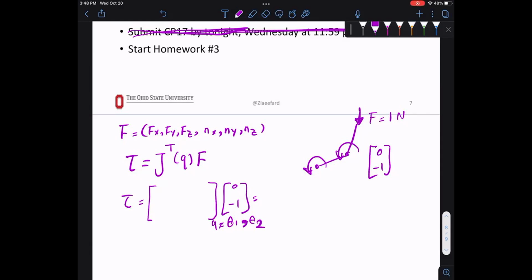So I just wanted you to think about it. Some of you are doing projects, and these are the things you want to think about if you're designing a robot. How do I use this course in real life? That's how. You're going to use the Jacobian in real life when you are trying to spec the motor. Or you can say, let's buy the most expensive one, $500, so it's not going to break. That's one way. The other way is to actually do the calculation properly, using the theory from this course, even though this is an introduction class, to do something that could have an effect in real life.